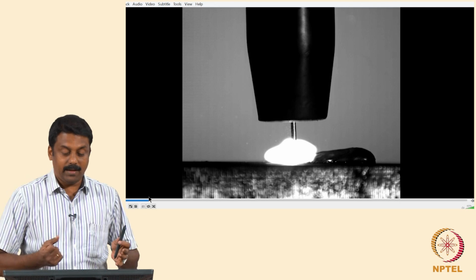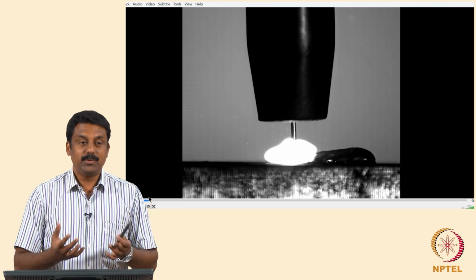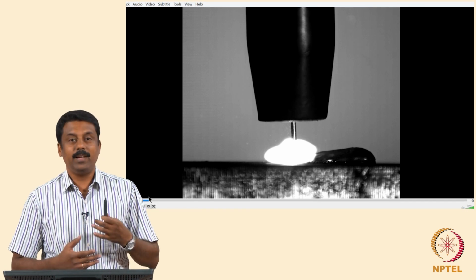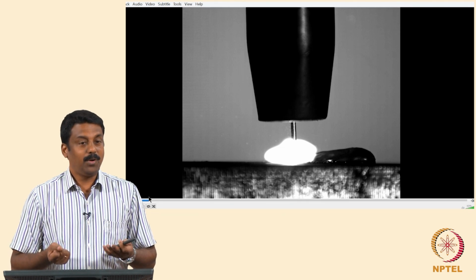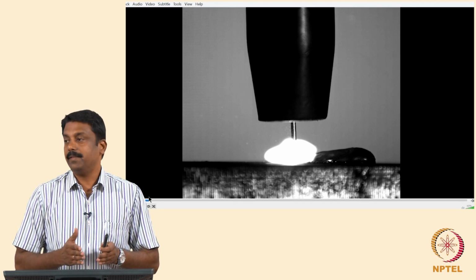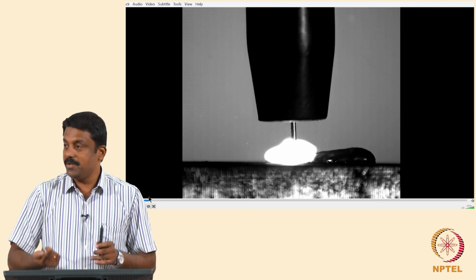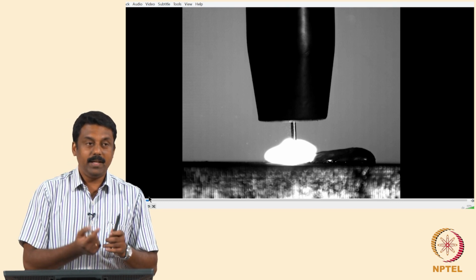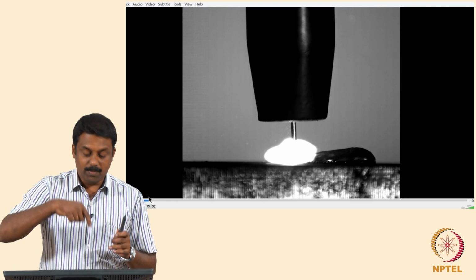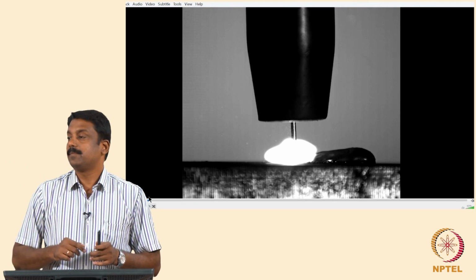So to achieve such a kind of complex metal transfer, the power source characteristics are extremely important, because the power source would also calculate how much it melts. The melting rate should be calculated accordingly. The wire feed rate must also be controlled, so that you can establish the short circuiting at a given defined interval. The moment short circuiting is established, again the power source should measure the voltage of the system, and the moment the voltage becomes extremely small, the current should be switched off, and then the droplet can be detached by retracting the wire back.